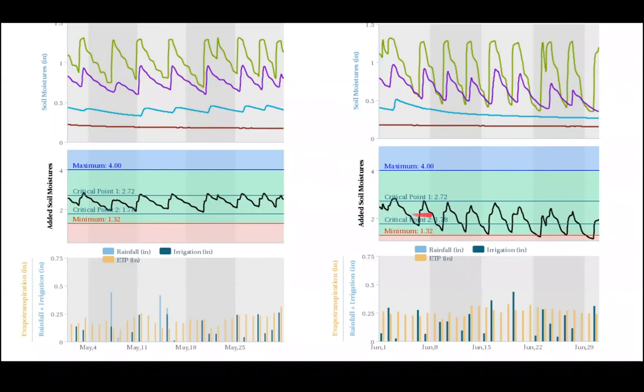And then 30 days after the fruit set, we cut back a little bit on the water in order to save a little bit of water. And overall, our moisture came down. The problem was when the soil moisture started hitting the red line here, and I started getting emails. So I started calling him and asking, hey, what's going on? You're not running enough. Oh, I'm running the 20 hours that we discussed, instead of 30 hours, we pushed it to 40, I think, but I'm running the same.